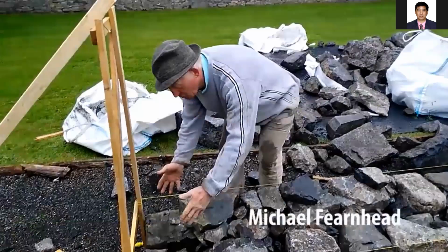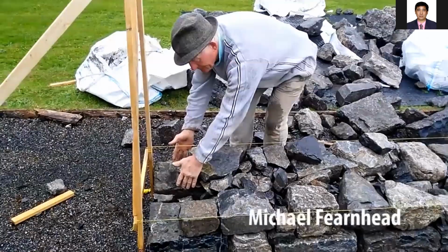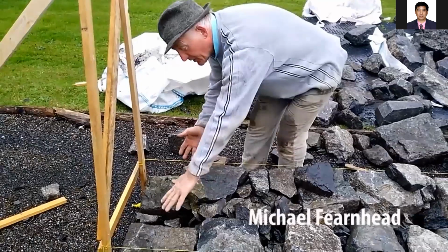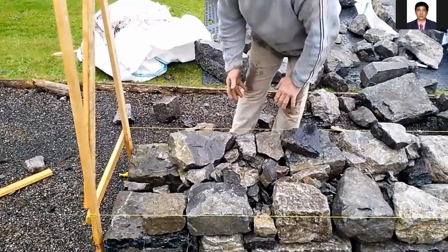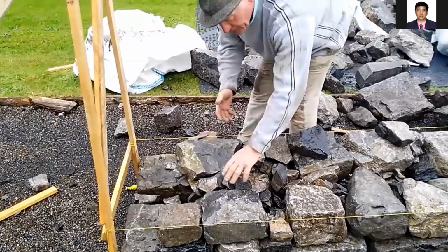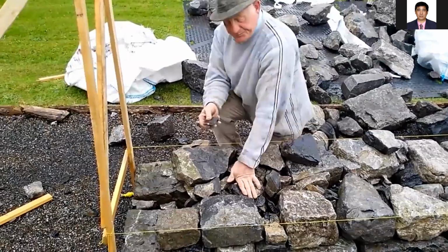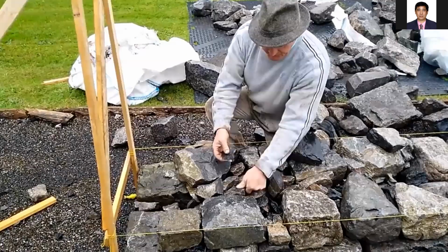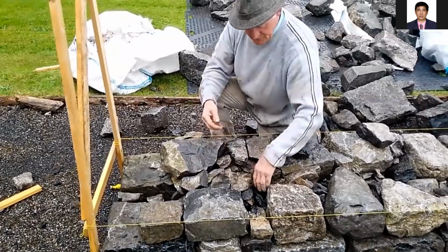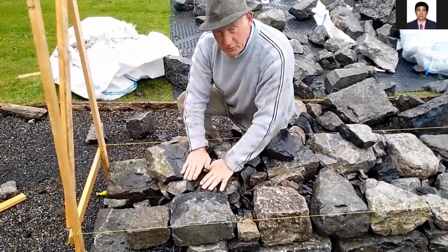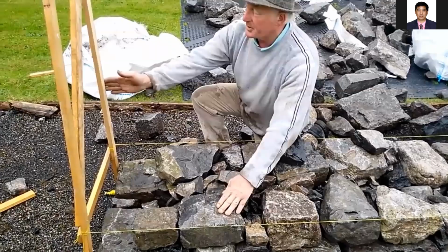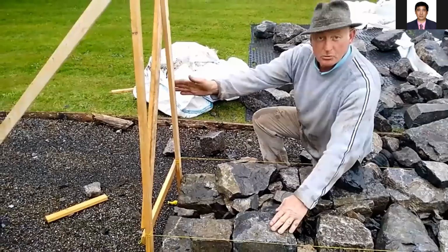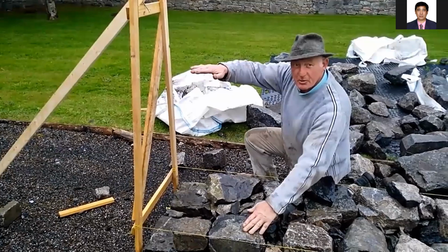There's the big stones in the bottom, and you try to get every stone as far into the middle of the wall as you can. You wouldn't have a long, thin one. And then, as you come up from there, you put your fillings in, you fill all the gaps in. You have to wall them, put them in flat, so they lay flat, so all the weight goes down on them. And as you come in with smaller stones, you have the batter on your wall. As you come up the wall, it gets narrower.